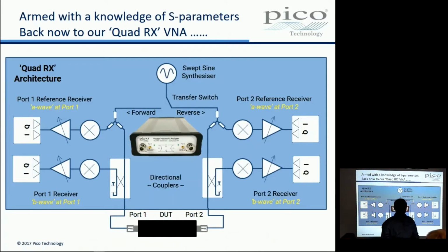Armed with the knowledge of S parameters, does that arm you with the knowledge of S parameters? Yeah. Got it? Yeah? And when the VNA106 saves an S parameter file, or Touchstone file rather, can you choose whether it's magnitude or is that fixed? It's real and imaginary at this point. One of our software enhancement requests is that you can change it, but when it saves and when you load, it's real and imaginary. Right, and there are utilities around to read and convert and all that. Yes.